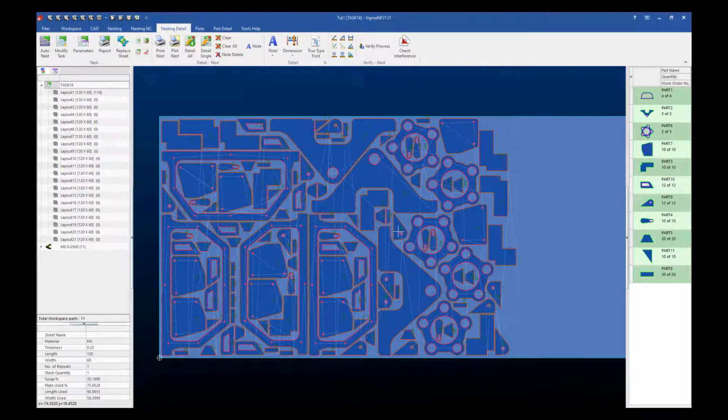So you come back to the software, and we see that we had about 1 hour and 11 minutes. So we're a little off. We're not too far off, but just enough that depending on how many parts, it can scale over multiple nests. So if I had 10 different sheets, that 10-minute variation is 100 minutes right there of time that could be lost. So that does compound. It might not sound like a lot for one nest, but over time it will compound and start pushing projects back and will cause a lot of issues in the long run.